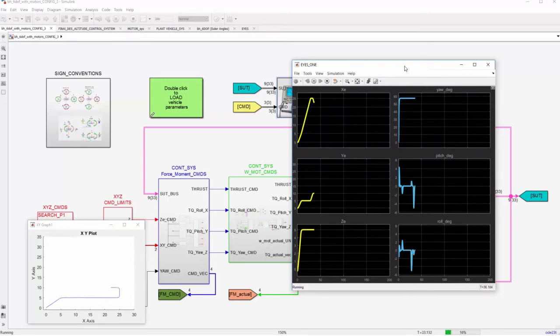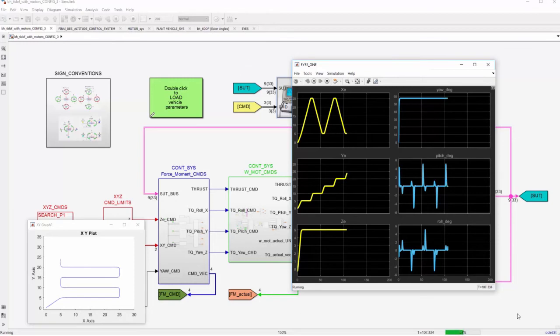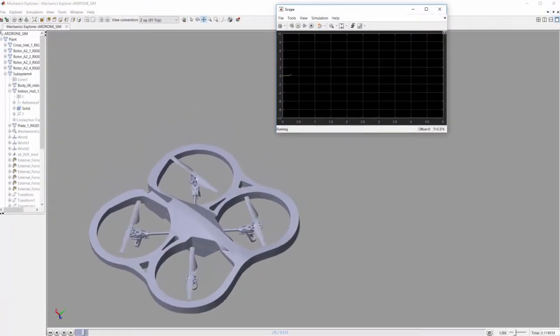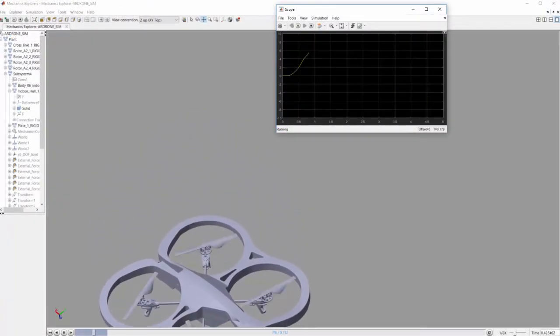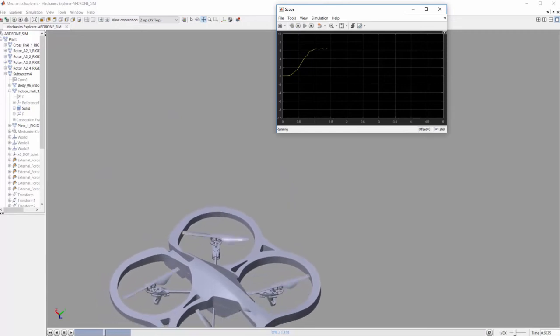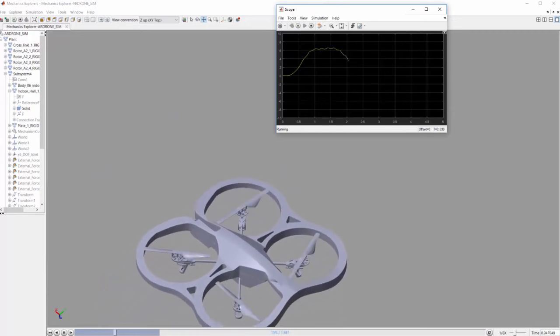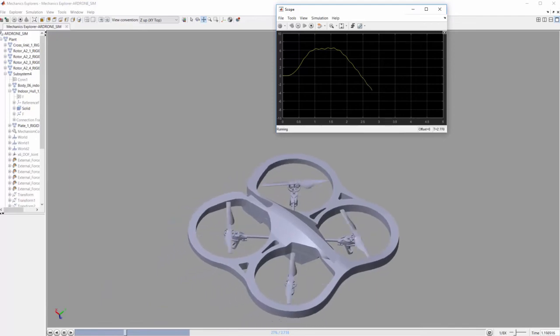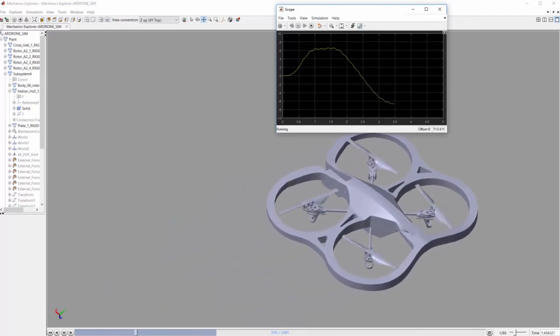In our example, we see a series of time traces for various properties of the quadcopter as the simulation is run. And, using Simulink, we can share the design with others in a standard block notation, so they can also check these results. We can configure our model to have just the right amount of detail in order to explore how our model works under many different conditions, and then iterate on the design before building a prototype.